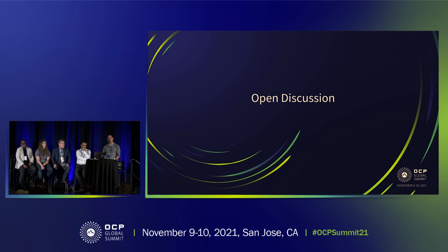Yeah, I perceive being nice with existing hardware, but do you want to push, I don't know, PCI Express Gen 6 to make I3C mandatory? Because there is a lot of inertia in the ecosystem. If there is no push from a standards body like the PCI Express group to say, hey, everybody, you should move to I3C, then you can have this mismatch that can stay and prevail for a long time. Yes, we are specifically working with PCI Express to officially make I3C part of their standard.